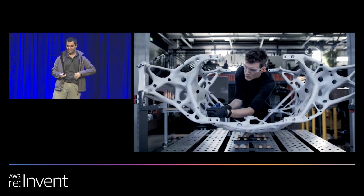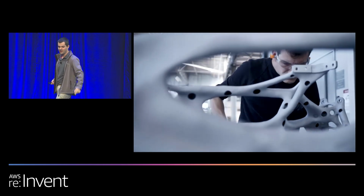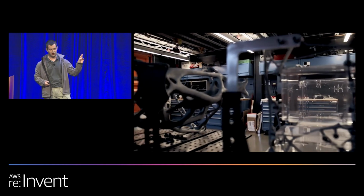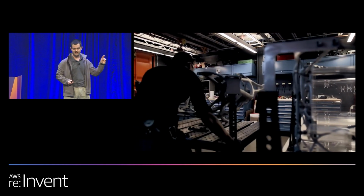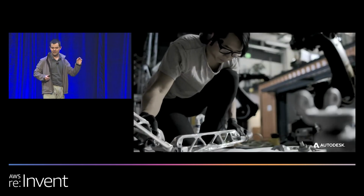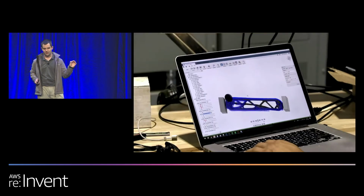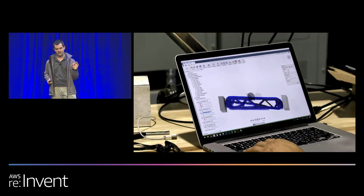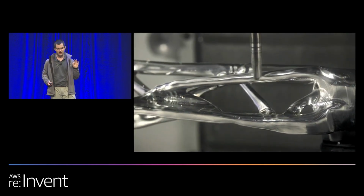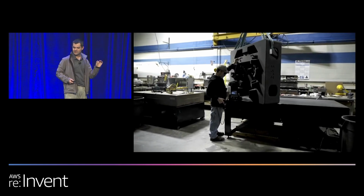Needless to say, JPL had to rethink the way things had always been done, and they decided to use generative design. Because generative technology in Fusion 360 is manufacturing aware, JPL could simultaneously explore a wide range of different materials and manufacturing methods, which meant that they could make the best choice for any given part on the lander. The legs of the lander were constrained to qualified materials and manufacturing methods, so they chose to go with a 3-axis milling strategy using aluminum. It made most sense for the external structure to be sand-casted due to the sheer size and complex technology.